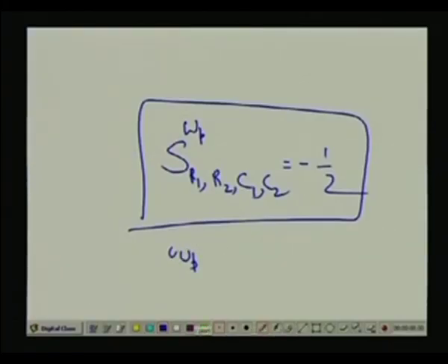Similarly, I can find the sensitivities of QP, right. Typically, in most of the transfer functions which you have written, the filter parameters we are more interested in are omega p, QP, capital K, and if possible omega z and QZ.